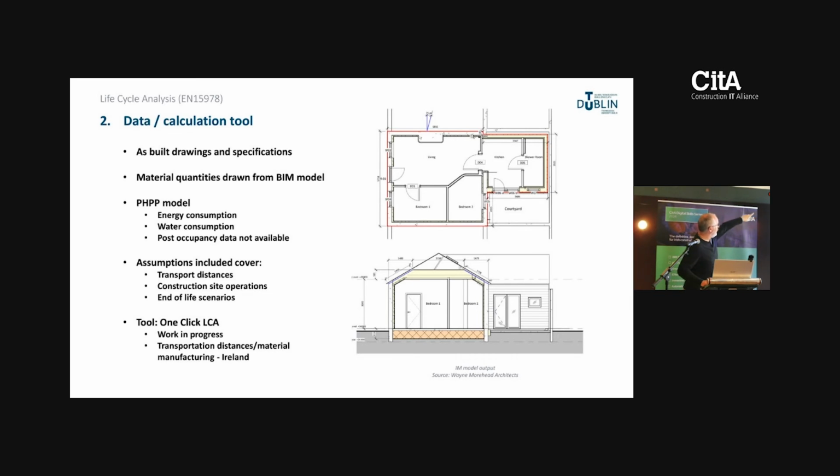We came in when we did this assessment at 322 kilograms of CO2 equivalent per meter squared, which comes in at a B grade across Europe of carbon efficiency. And if you can see down below there, it's well below a pathway that's taking us to net zero, according to what's called the carbon law, which I won't talk about now.